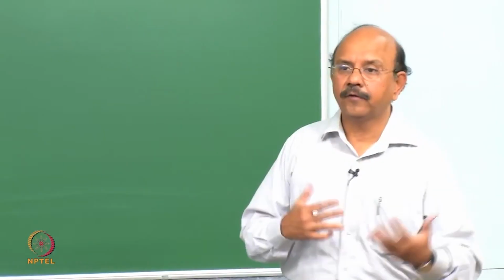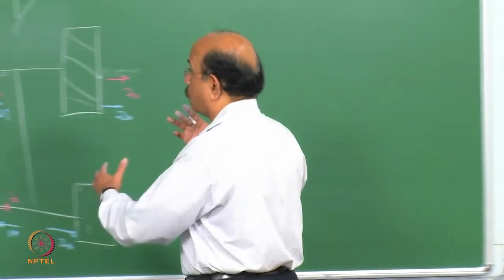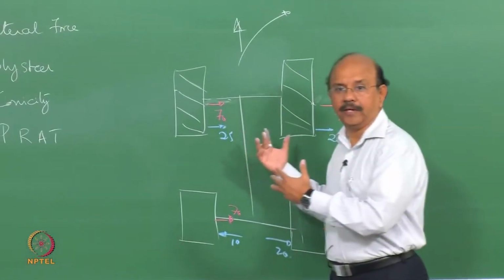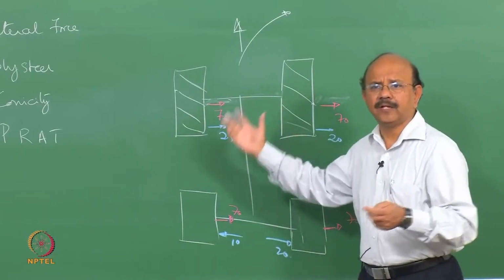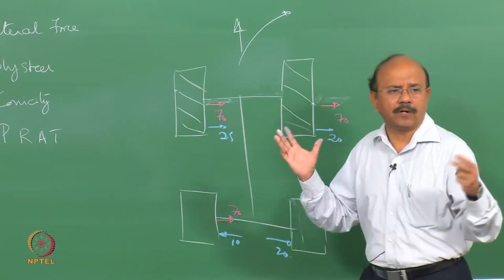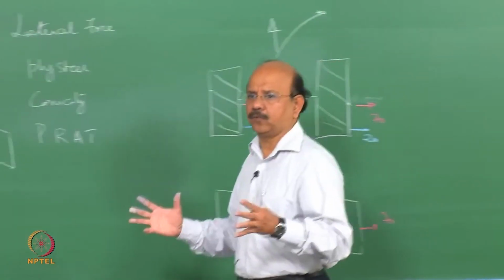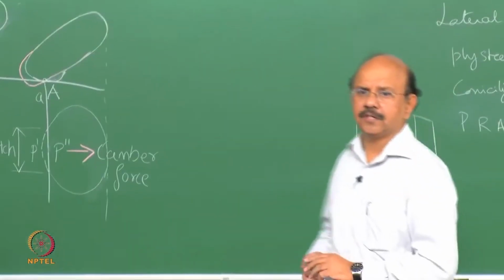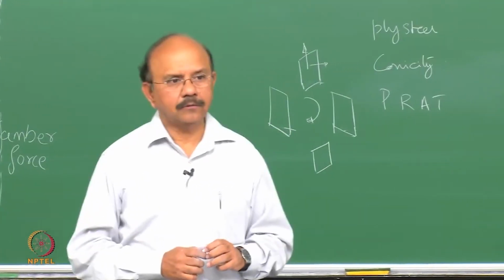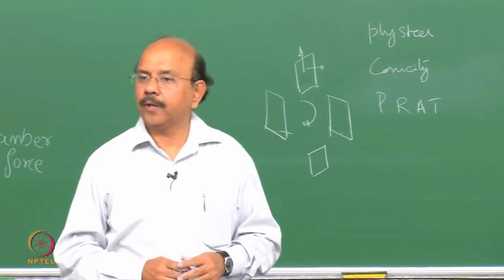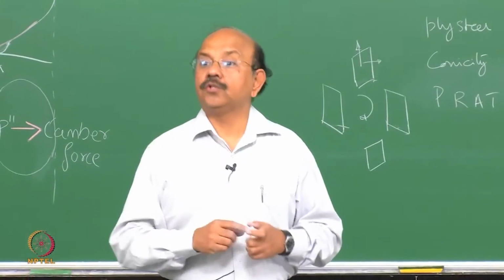Okay, these kinds of forces would cause wear, and that's the reason why wear will depend upon whether it's a front or the rear, and that's the reason why there is always a rotation, what the tire companies call a rotation plan, so that the forces that are generated do not accentuate the wear of the tires. Right? So this is the effect.